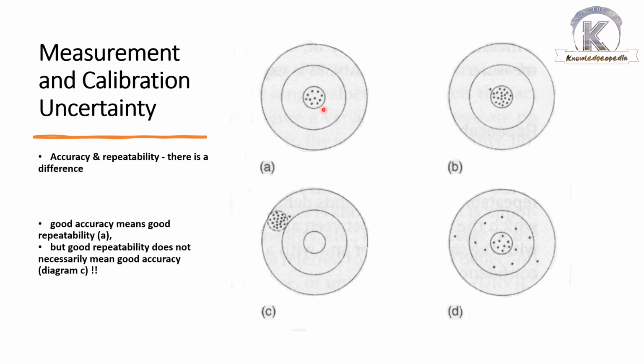Suppose out of the n number of meters installed in a particular filling machine, one or two meters are not exactly accurate. That means what? Out of 200 ml, those flow meters are passing 170 ml of Coke into a bottle. So you need to compensate that 30 ml shortfall, again and again, whenever any empty bottle comes through that particular flow meter.